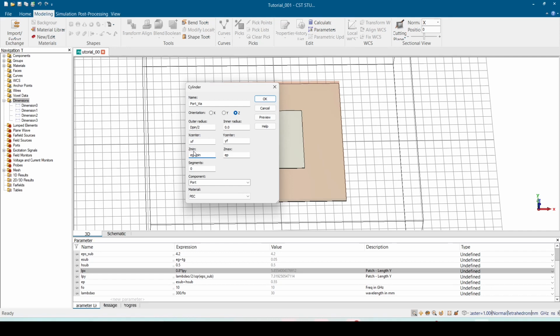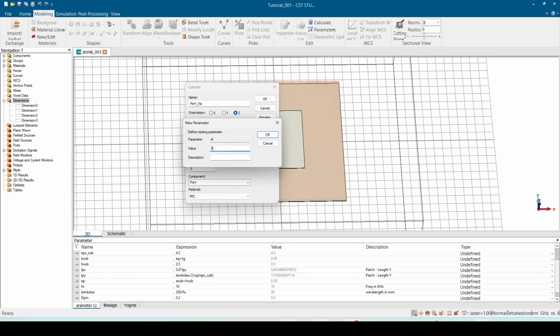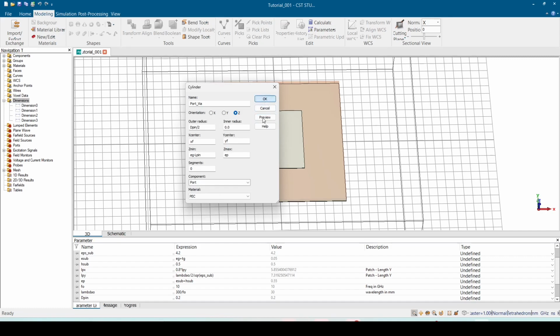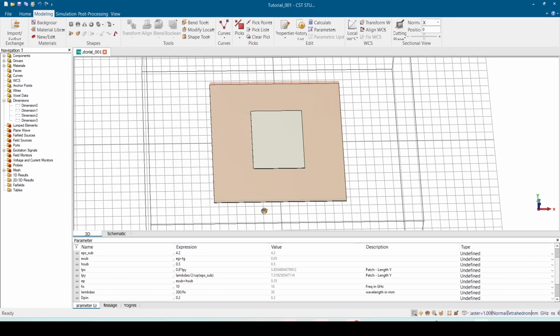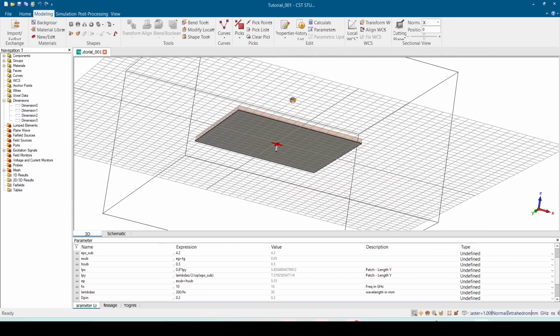This is the extra or excess length below the elevation of the ground, right? And then we can set generally anything. For now I can say 0.2, x 0, y 0. This will be changed later, of course, and I will do like 1. Okay, and press OK. So what we did is that we created a pin like this.